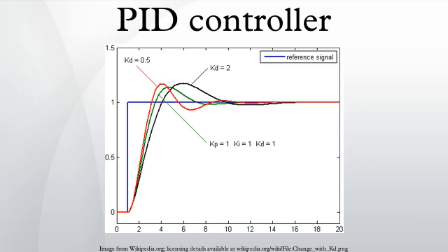Optimum behavior. The optimum behavior on a process change or set point change varies depending on the application. 2 basic requirements are regulation and command tracking. These refer to how well the controlled variable tracks the desired value. Specific criteria for command tracking include rise time and settling time. Some processes must not allow an overshoot of the process variable beyond the set point if, for example, this would be unsafe. Other processes must minimize the energy expended in reaching a new set point.